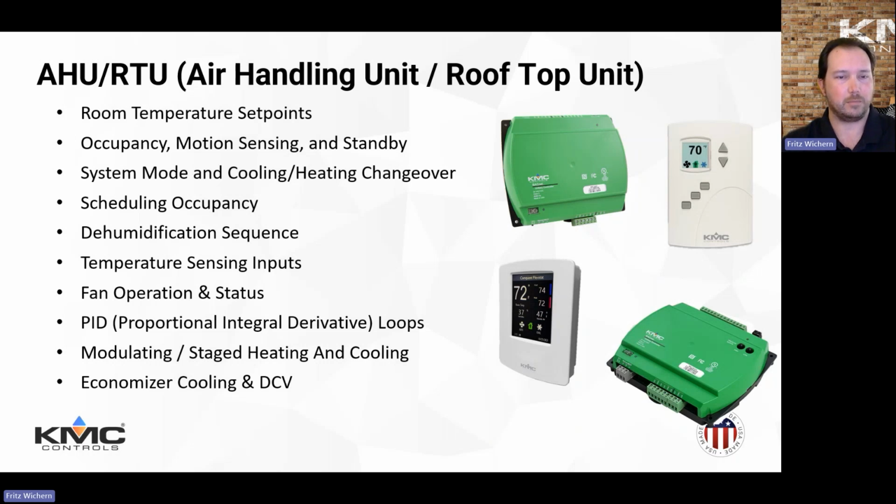Again, we're using the same standard set points across the board, motion sensors for occupancy and standby. The dehumidification, same as the other applications. Temperature sensing inputs, we've still got looking at space temp, discharge air temp for economizer control. The outside air temp is required for economizer and compressor lockout.